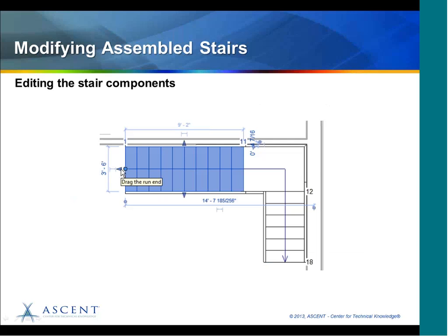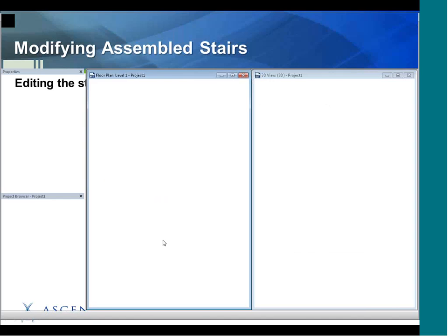As you can see here, I think it's a little easier to see on this than when I actually do the demo. We can, once again, change the width of the stair. We cannot change the length, though. So the stair components are not changeable. It's telling us what it is, but it is not changeable. We have these grips right here, the controls, and I'm going to show you how these controls are different. Very important part of working with them as well.